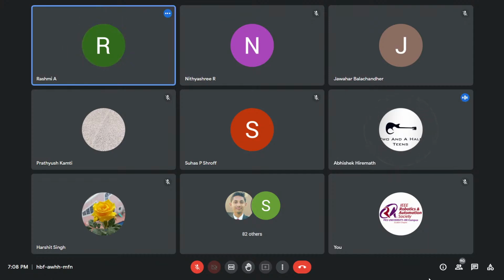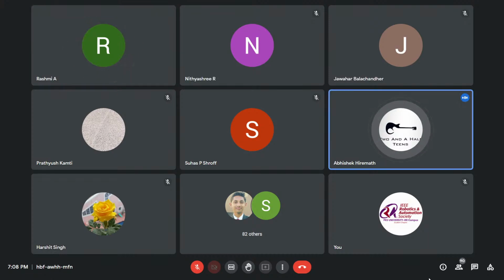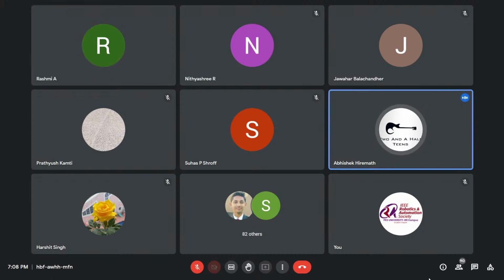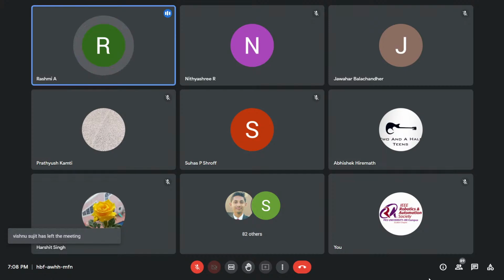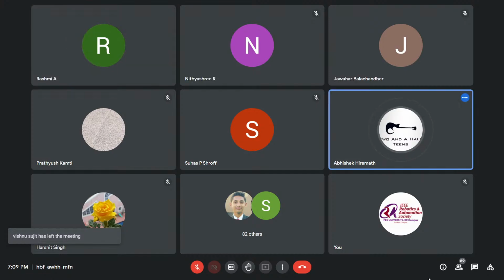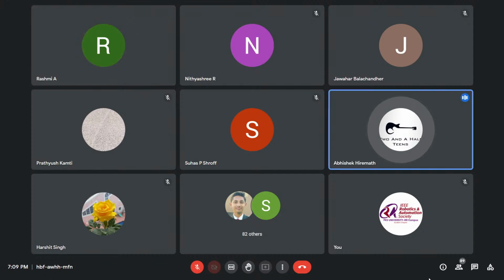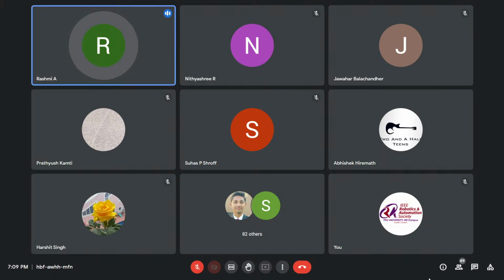And then you have to go to Tools, then Board. You'll get an option called Board Manager. Click on that and just type out ESP8266. As simple as that.